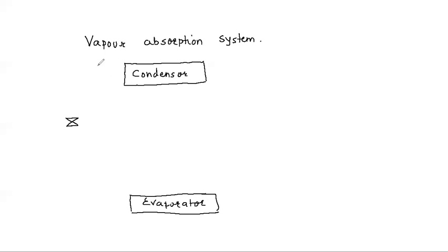Okay. So the refrigerant from the condenser would go into the expansion device. And from the expansion device, this refrigerant would get back to the evaporator. So this is similar to the vapor compression refrigeration system. This portion which I have drawn is similar to the vapor compression refrigeration system. Okay, now what next? As I said, we will not have a compressor here, but instead of the compressor,